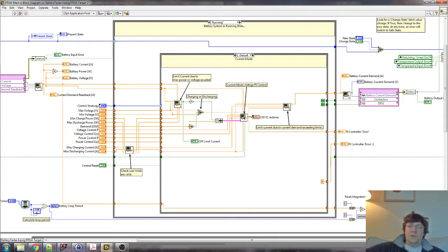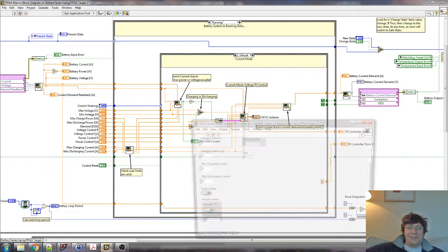But if you just cut the controller in cold turkey at the moment where you need to go from current mode to voltage mode, the controller's going to have a transient, and you won't get data that you'd like to see. The controller has to be watching effectively from before, so it can see it coming, because it doesn't see the future, that's not how it works, but you know what I mean.